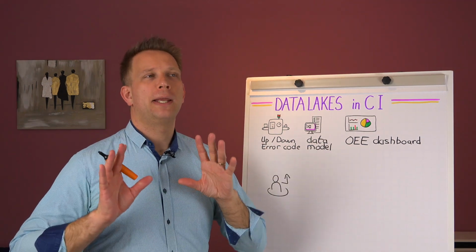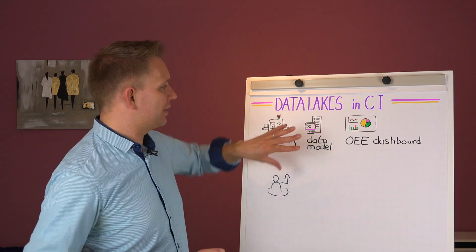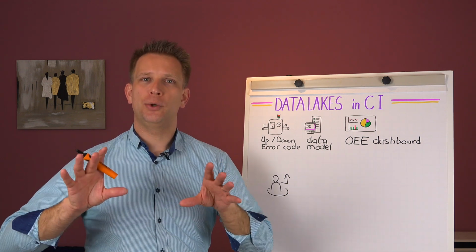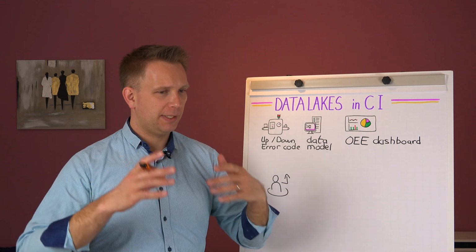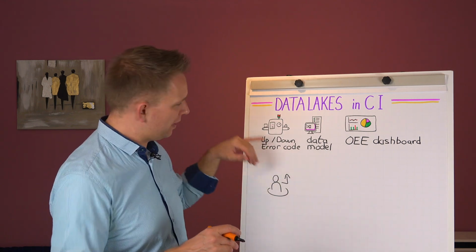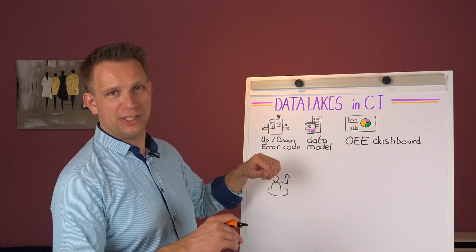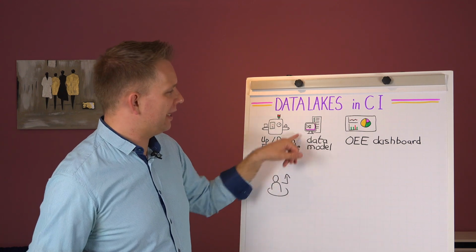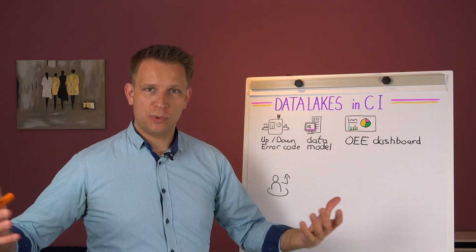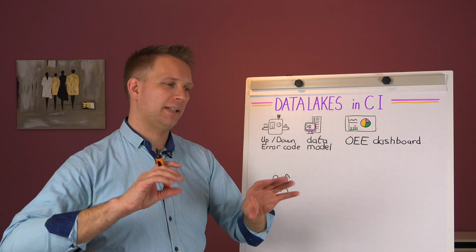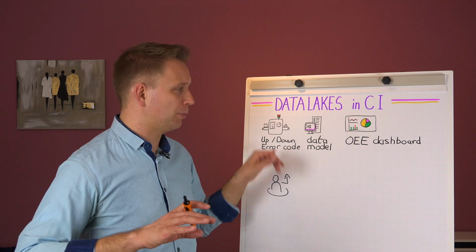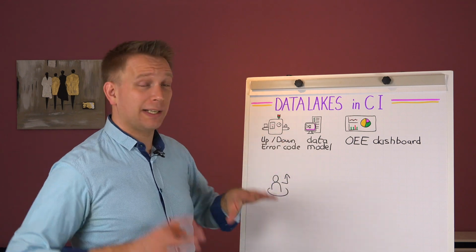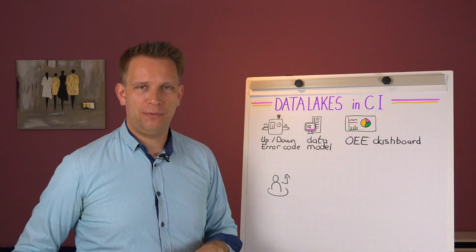And when we just put a piece of OEE software in place, what we get is a nice data model that is pre-populated with ways to calculate OEE. So you get your minutes that your machine is running, your minutes that your machine was down for error code 365, your minutes that your machine was down for error code 247, all kinds of input like that, and you need to connect it into meaning. So you build this data model that says, I've got a production run, that's so many minutes, I've got a nameplate capacity of the line, so anytime we're making products, we take the product counter divided by so many products per minute to get how many effective minutes it was doing, and then we can calculate percentages and make a nice dashboard out of it.